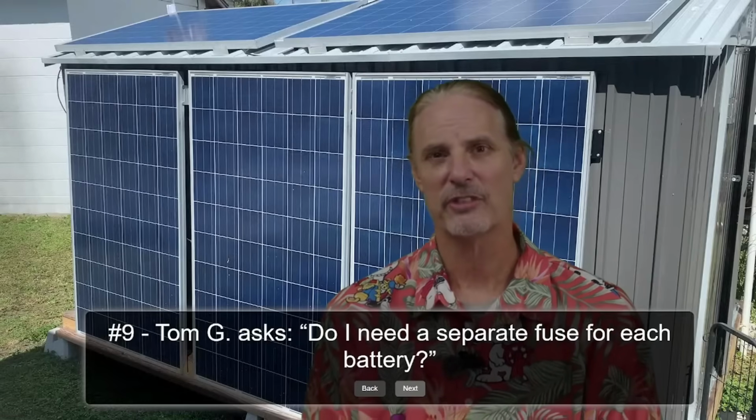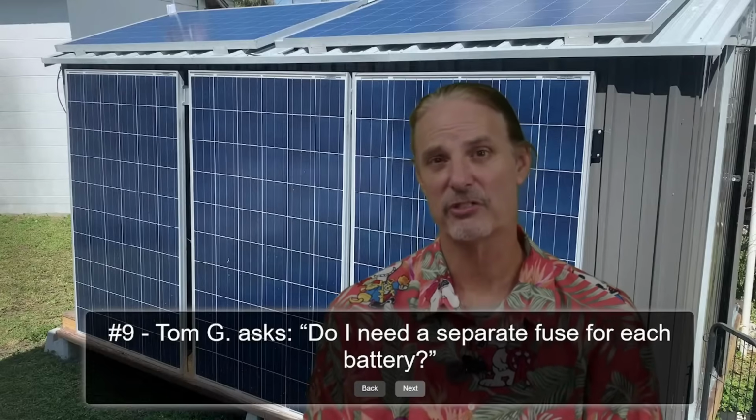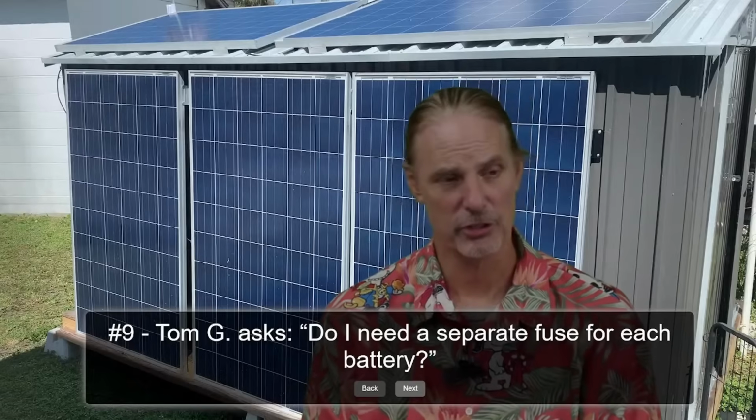So I always suggest that batteries be fused with something that has a response time fast enough. A T-class fuse is my suggestion there.